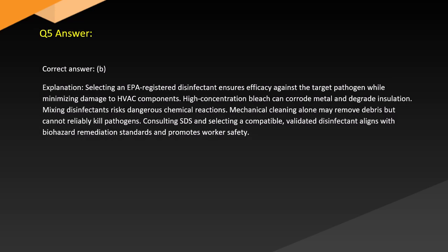Answer. Correct answer: B. Explanation. Selecting an EPA-registered disinfectant ensures efficacy against the target pathogen while minimizing damage to HVAC components. High-concentration bleach can corrode metal and degrade insulation. Mixing disinfectants risks dangerous chemical reactions. Mechanical cleaning alone may remove debris but cannot reliably kill pathogens. Consulting the SDS and selecting a compatible, validated disinfectant aligns with biohazard remediation standards and promotes worker safety.